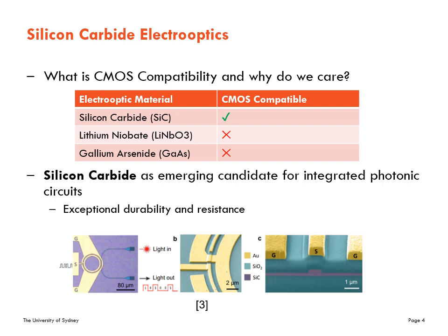Silicon carbide is an emerging material in photonics research. It is a CMOS-compatible material, exhibits the linear electro-optic effect, and has exceptional electrical, mechanical, and radiation durability. These characteristics, along with the material's low optical loss, wide optical transparency window, and high breakdown voltage, indicate great potential for silicon carbide in CMOS electro-optics.